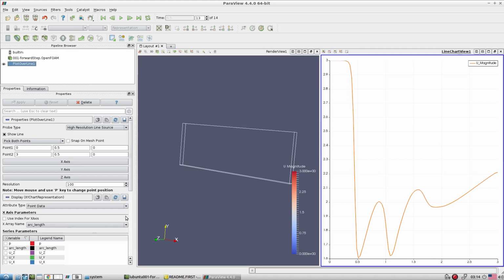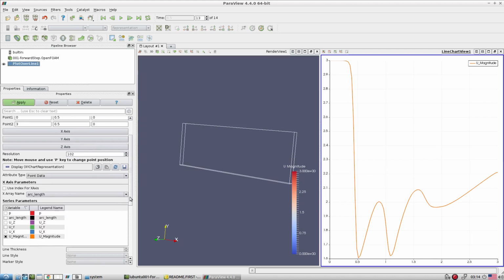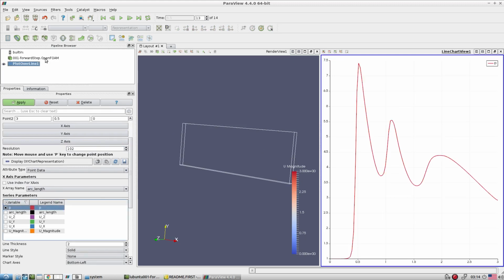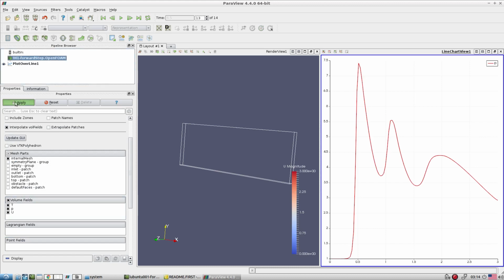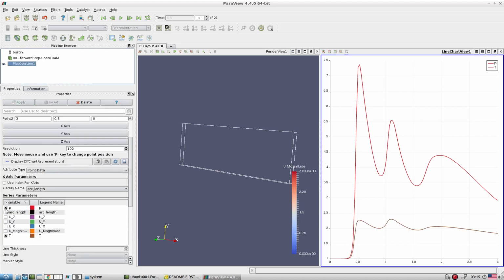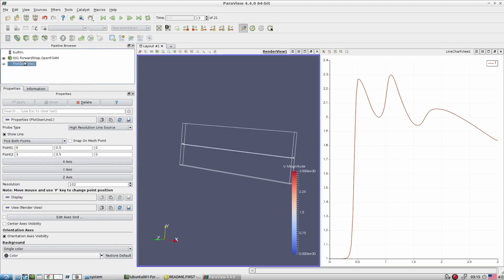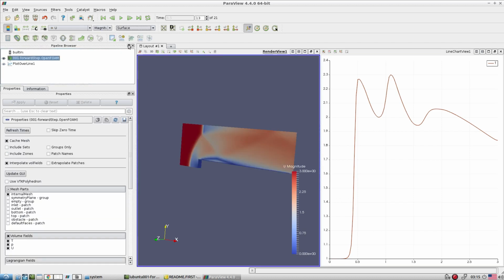What I am observing right now is the velocity magnitude, and then we have pressure as well, how pressure is changing. If you want, you can activate the temperature from here, and then you can see the temperature variation as well. At the shock you have an immediate jump in all the properties. That is exactly what is happening at these locations. We have immediately sharp change in the property above and below.